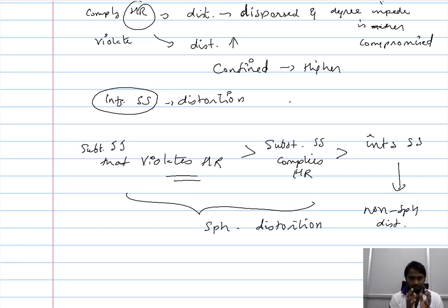So what we have essentially seen is that it is possible for us to enhance the high temperature life of the material by decreasing the plastic deformation the material experiences within the steady state condition at a given point. One way of doing that is introducing a solute, and this solute introduces a distortion to the lattice of the base metal, and because of this distortion, the propagation of the dislocation is impeded, because this distortion brought about by the solute should interact with the distortion brought about by the dislocation. Because of this complex interaction, the rate at which the dislocation propagates is impeded. Even though this principle remains the same, there are different degrees to which these solutes impede the dislocation.